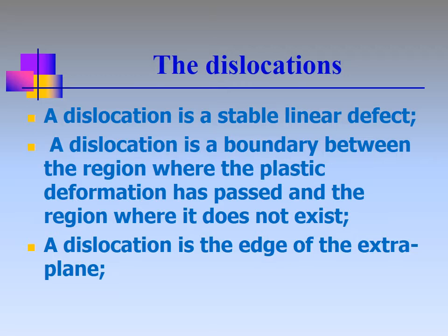A dislocation is a linear imperfection such as the breakage or shear of atomic layers, which disrupts correctness of their alternation in the lattice. As noted above, plastic deformation in a crystal does not occur instantaneously but gradually along certain atomic planes in certain directions.